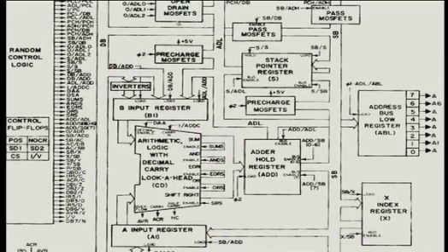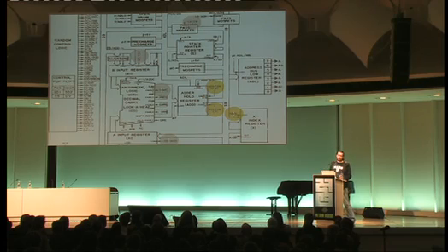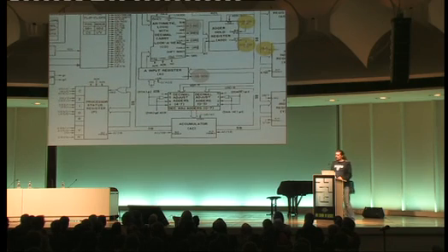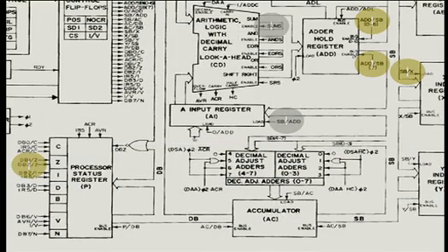Then in the second cycle, we have to get the add or hold register output, put it onto the S bus with these two control lines, and we store it into X in there. There are a few more bogus junk control lines there to keep the ALU occupied, which are a side effect of how everything is encoded, and the way the don't care works. So this doesn't have any influence on what's actually going on. But there are two more lines that are asserted: the one that sets the zero flag, and the other one that sets the negative flag from the output.